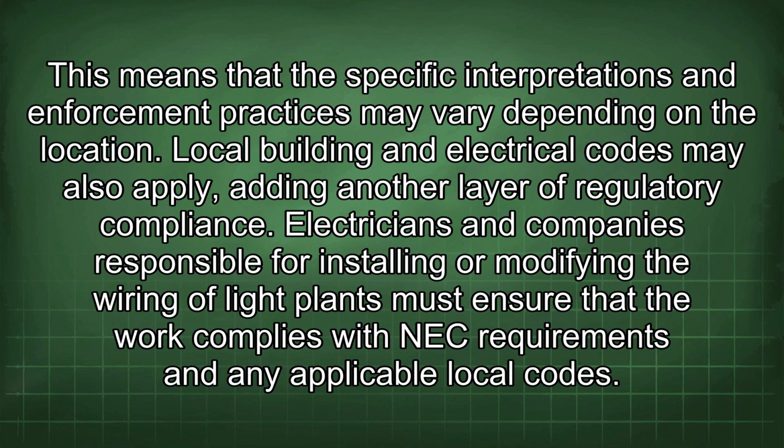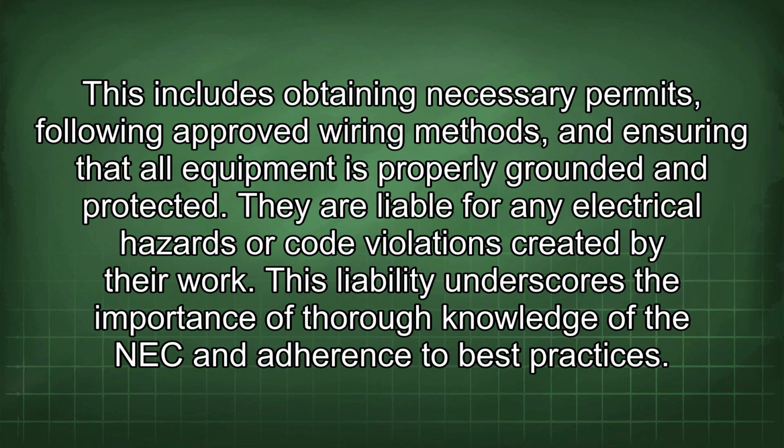Electricians and companies responsible for installing or modifying the wiring of light plants must ensure that the work complies with NEC requirements and any applicable local codes. This includes obtaining necessary permits, following approved wiring methods, and ensuring that all equipment is properly grounded and protected.